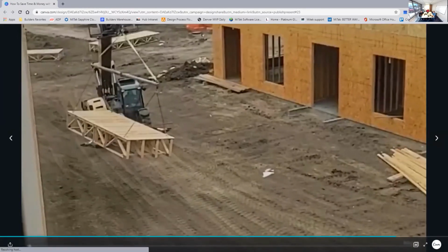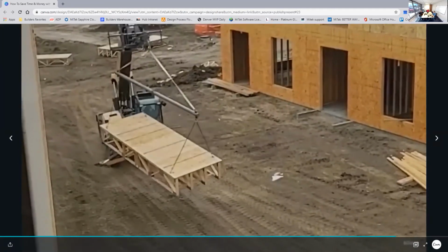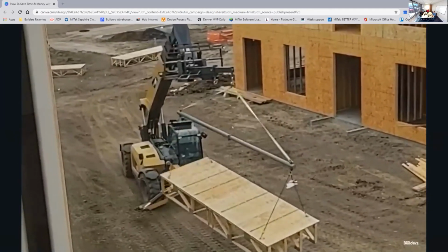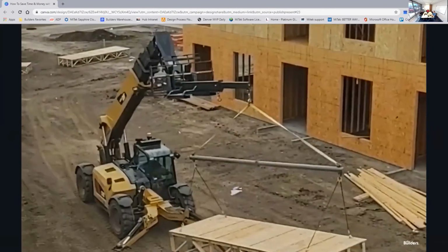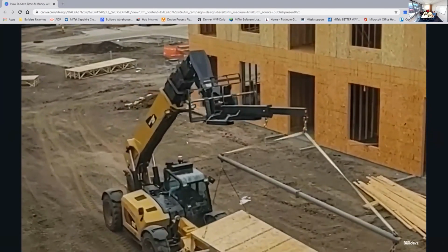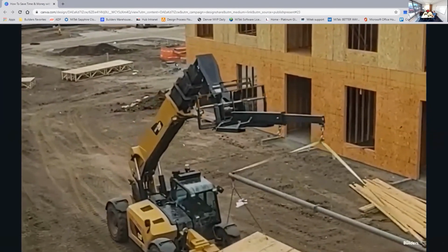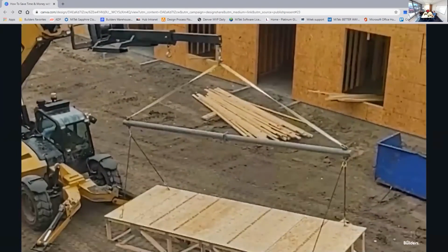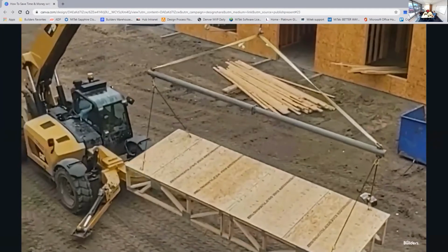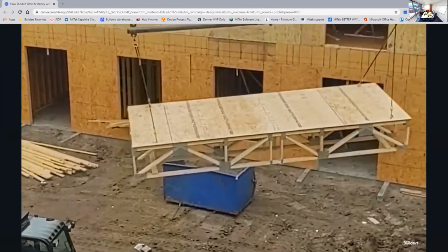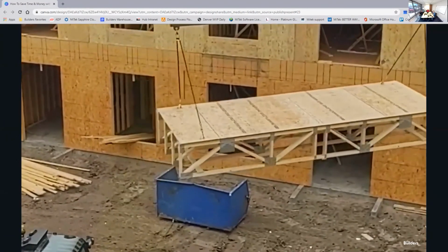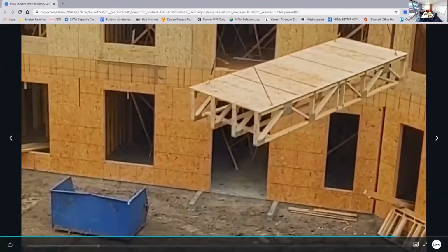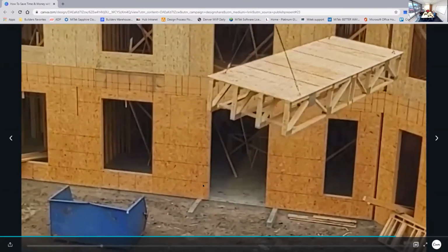Okay, there you go. This is an example: we will sheathe that deck and then they will crane that up to whatever floor is needed, and the sheathing will be installed. On a multifamily project, per floor, it has saved them up to 6 to 7 working days worth of work, completely minimizing the time it takes to go from first floor to roof, which has substantial savings.